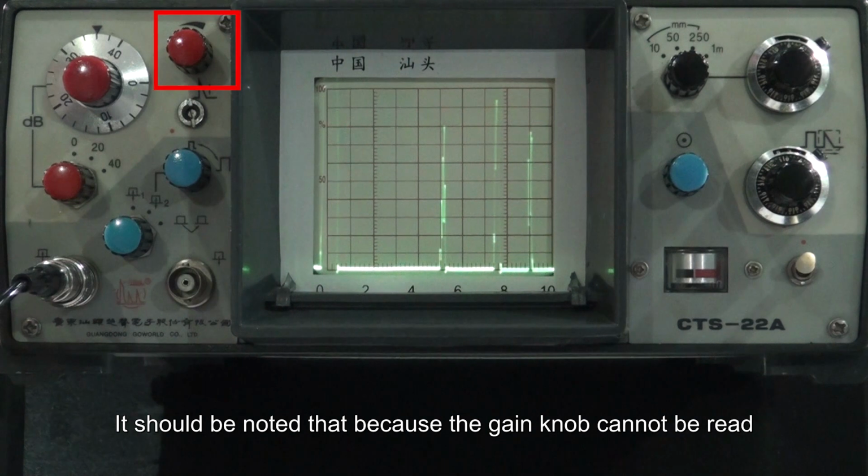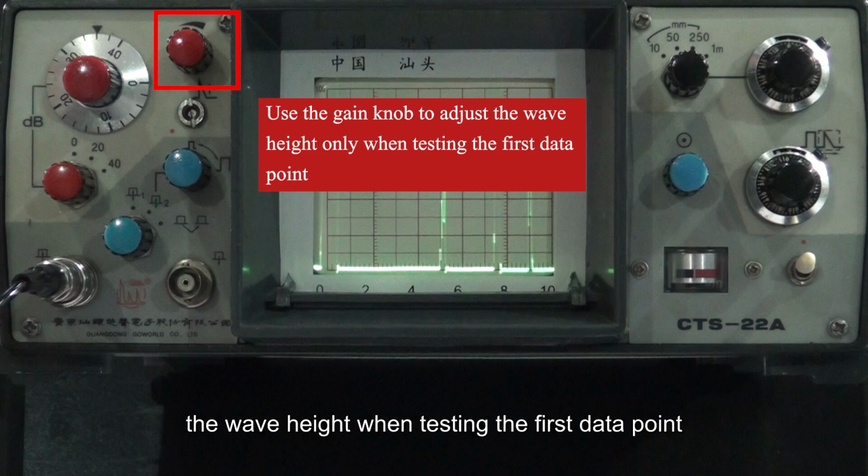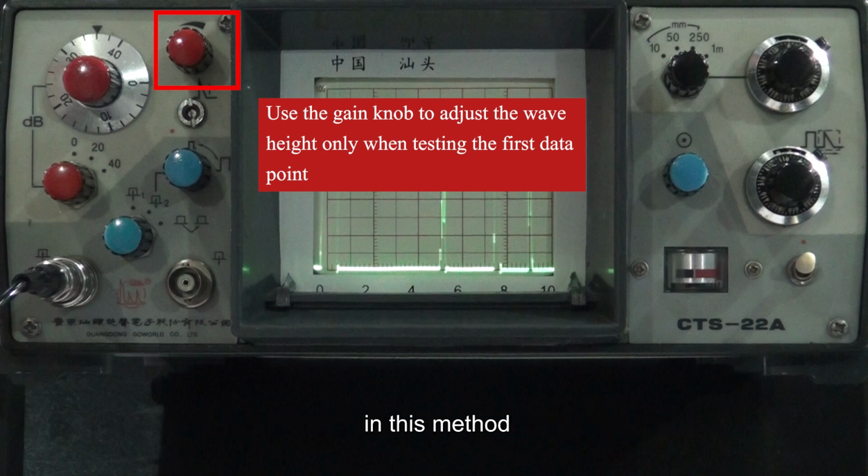It should be noted that because the gain knob cannot be read, the gain knob can only be used to adjust the wave height when testing the first data point in this method. When testing other data points, the gain knob is not used and other data points are tested based on the same gain value.